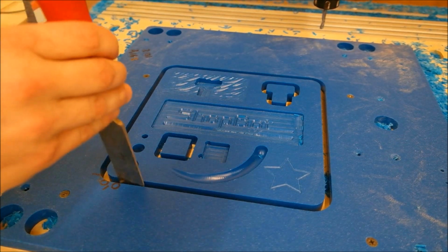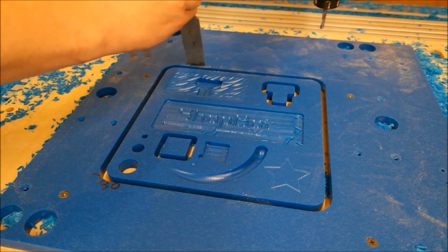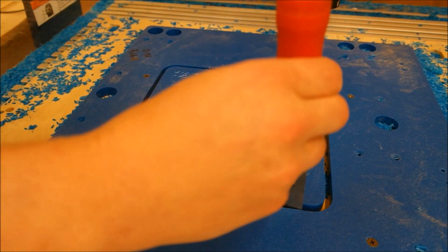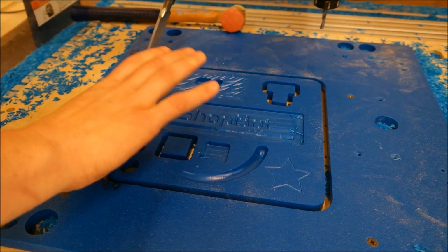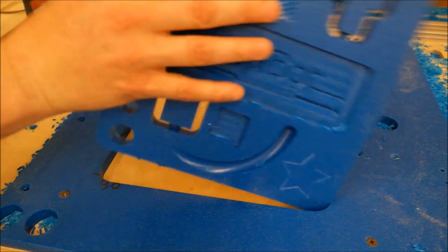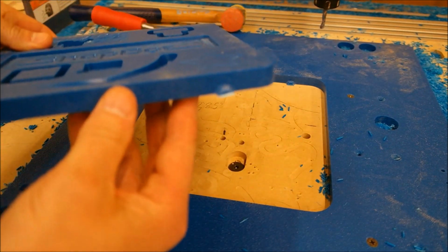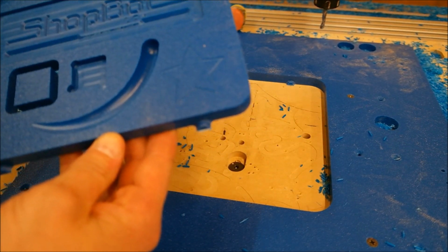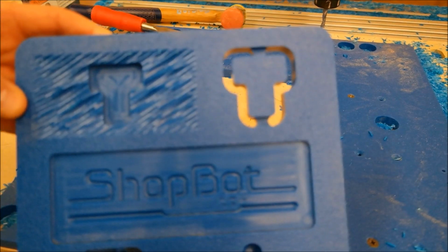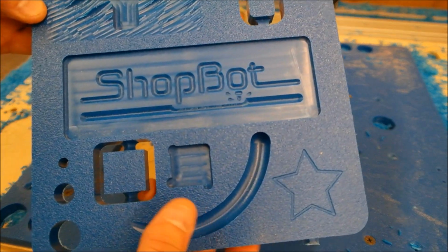Then once the cut is done, you do need to remove the tabs. You just use a chisel here in place, or I'll take it off, flip it over, and nip it with the utility knife from the back side. And then whatever little tab remnants are left, that's where you do need to sand, or I like to take it over to a flush cut router and put a straight edge on it, and that way it doesn't leave any debris or any machine marks.